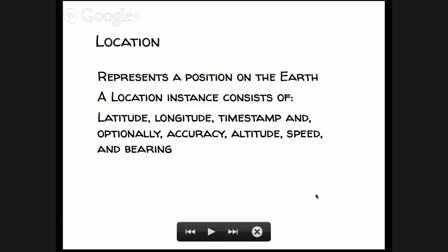What if I'm seeing, let's say, 20 satellites as compared to 5 satellites? What will happen? Your accuracy will vary. If you are seeing more satellites, then your intersection area and your confidence in it increases. But if you see fewer and fewer satellites, for example, in this area, your GPS knows that it is trying to get a location by finding the intersection, but it says the accuracy is low. I'm not seeing that many satellites.